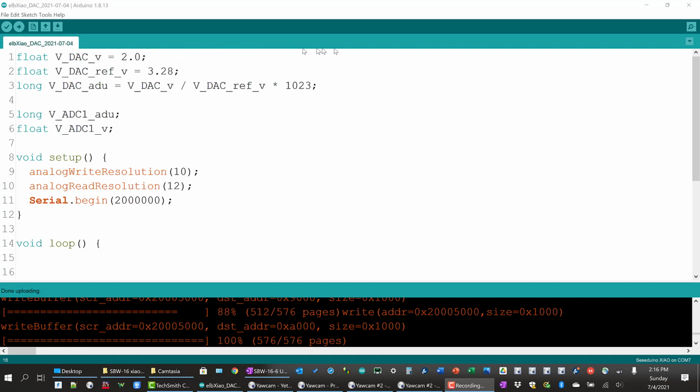You notice at the very top of the screen, off to the far right, the little pull down arrow. So we are going to pull that arrow down, and we're going to create a new tab. And it's in the tabs that we store the functions. When we save the sketch, the functions will be saved as separate files that will be called by the main loop. So very simple. We create a new tab.